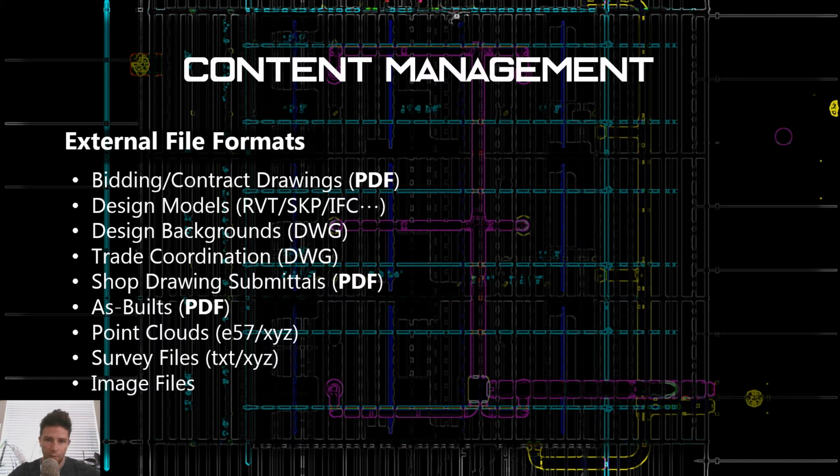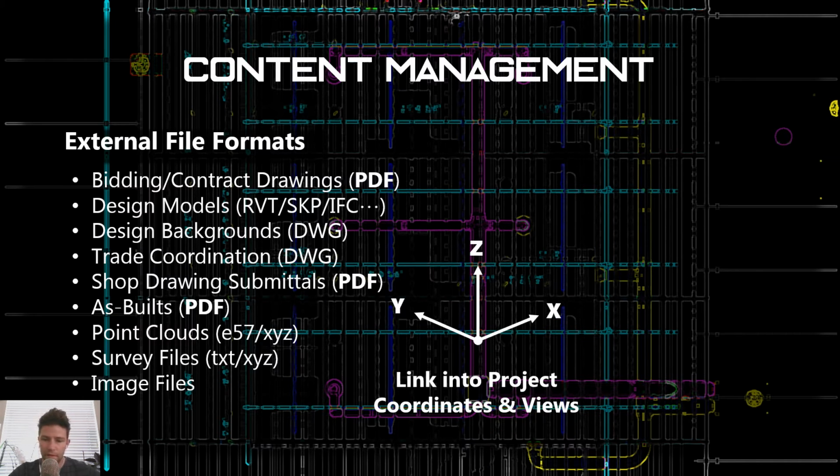And then of course we have other file formats, whether it's point clouds, survey files, or image files, and we can bring all of these together. So really, the whole step for me is whatever format, whatever information you have at that point in time, it might be limited, it might be extensive, the ability to take all those different types of content and bring them into a virtual project within ArchiCAD, and place them in the correct positioning, in scale, and in the correct coordinates, is a way to really enhance your ability to interact with those different formats and take a step forward in being able to review them thoroughly.